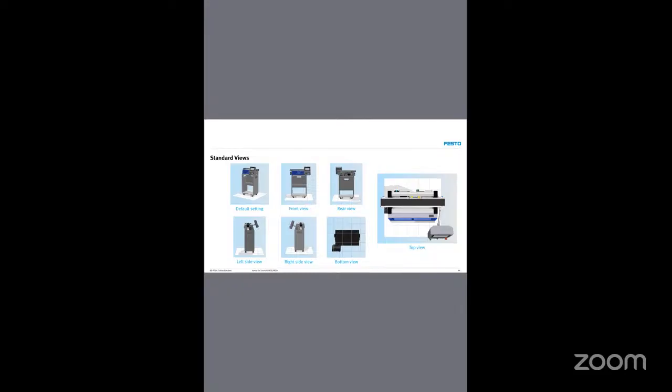Based on your requirement, you can select the view. For example, default view is what you see if you open Ciros, the default setting. If you want to see the front side, you can select the front view. If you want to see the sensors, motors, wiring, etc., select the rear view. Then to see the left, click the left side view, and click right side view to see the right, and the bottom view to see the bottom parts. So this is the main view. During the factory layout, you are going to use this top view.